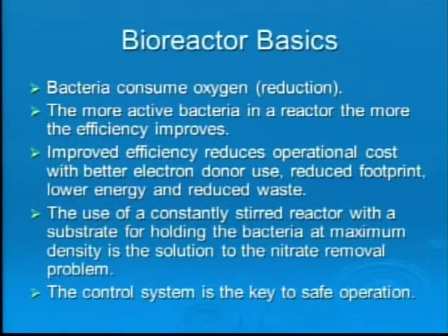Again, real simple. The whole idea is that the bacteria consume the oxygen. They're breathing it. What we do is force them to take the oxygen off of nitrate or some of the other materials. One of the things that we based our system design on was work done primarily by the Japanese to improve the performance of existing wastewater treatment plants. They found that by using a carrier to build the bacteria and circulating that bacteria in a constantly stirred reactor, they got enhanced performance of the system.